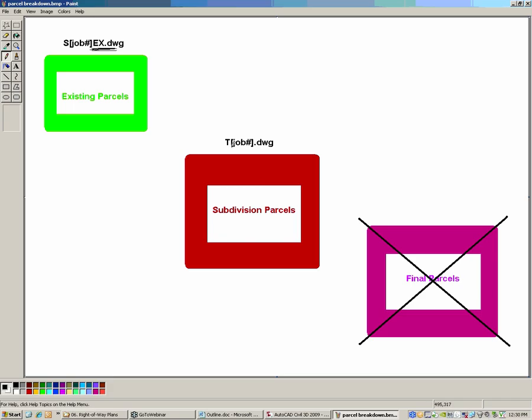The subdivision set, or the set for the take, where we're going to pull out the different values for area and see how it affects all the parcels, that's going to be a whole different set of parcel data. So you do have, essentially, some tracing over top of the different parcel sets. And then the final, that's more for land development. I don't think on right-of-way takes that you guys actually show the final, what it needs to be at the end of the day after the take, a clean map just showing the new right-of-way in that take. But if you'd want to label the areas for that, what the property owner would have after this take takes place, you'd have a final set of parcels.